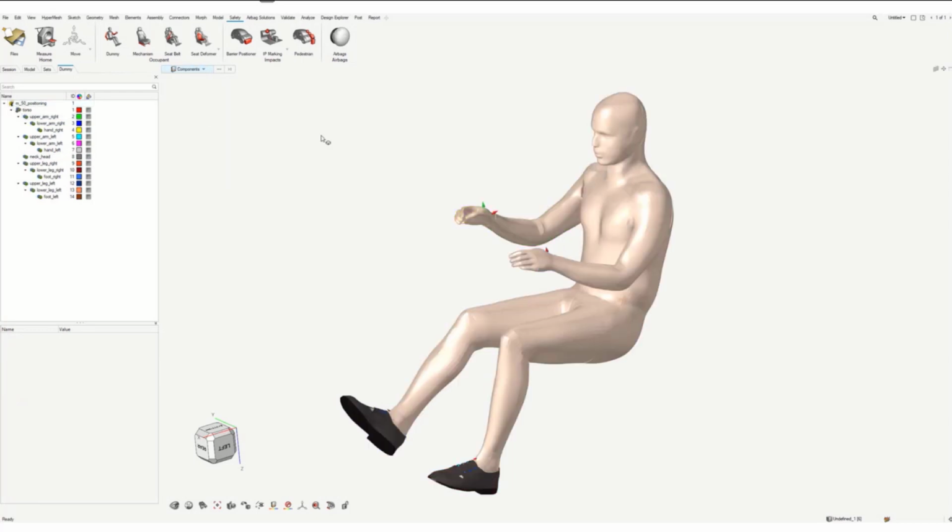And from the dummy positioning tool, you will have access to all the actual functionalities which are already implemented. So, for example, the pre-simulation, which in that case must be performed, because the human body model, once you position it, the mesh of the dummy model is, I will not say optimal, and you may have also intersections and penetrations with other parts. So you will have the same functionalities as for the standard crash dummies, the ability to export a pre-simulation that you will run then with the solver to get the correct positioning of the HBM.